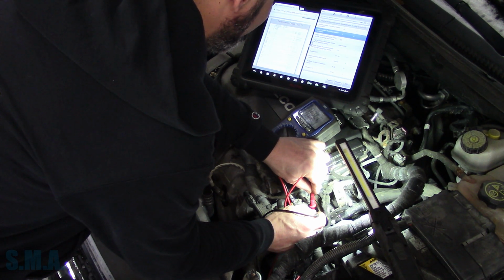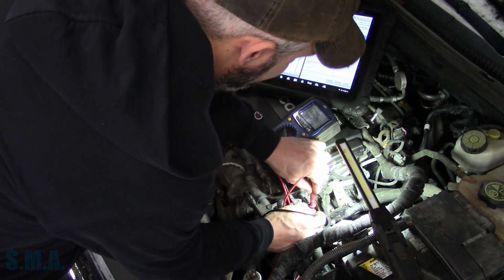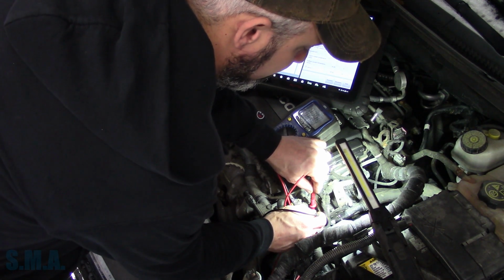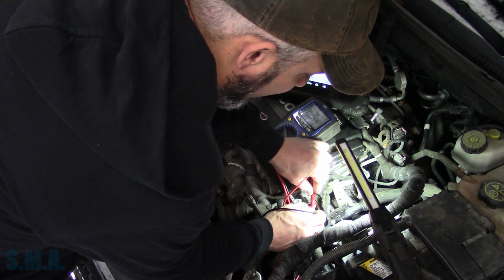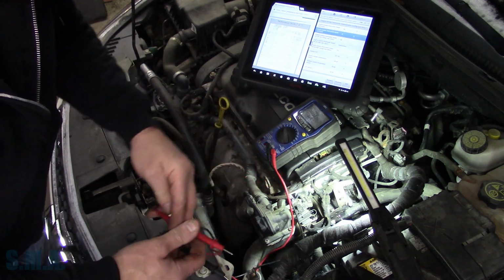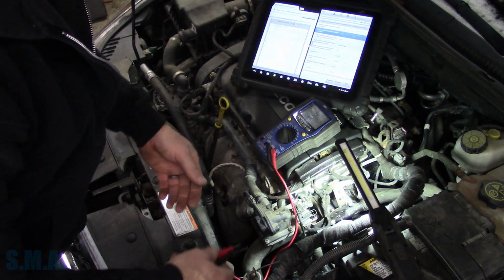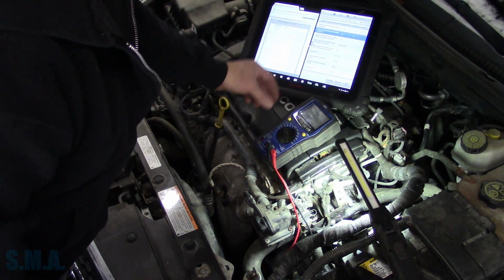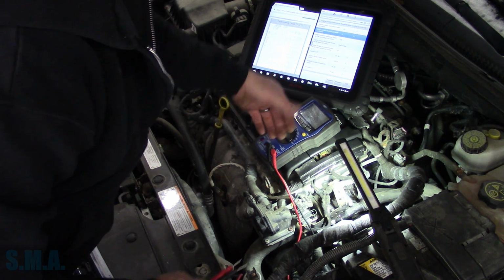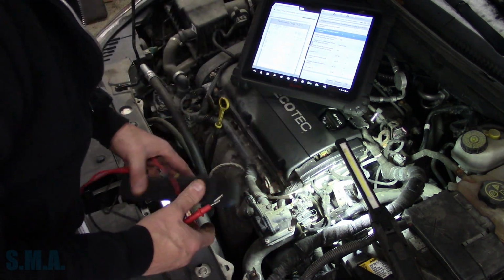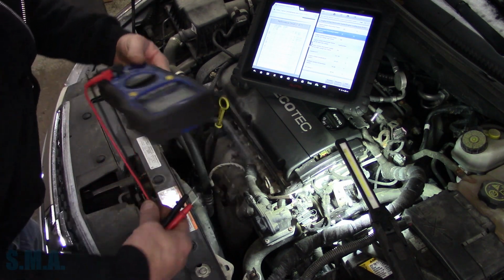So about 86 right now, 87 and climbing. So 88,000 ohms. And we know that's way too high to make any heater work. I would imagine this thing would be at 30 ohms, something like that. Definitely not 88,000. So piece of cake, easy 1-2 diag.